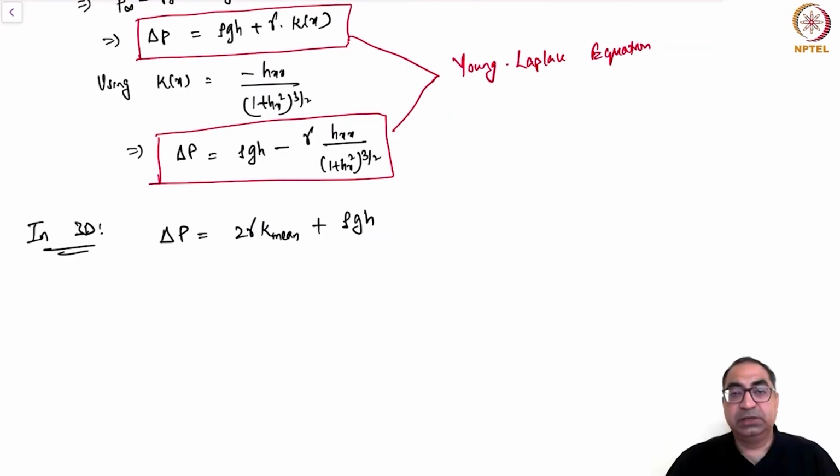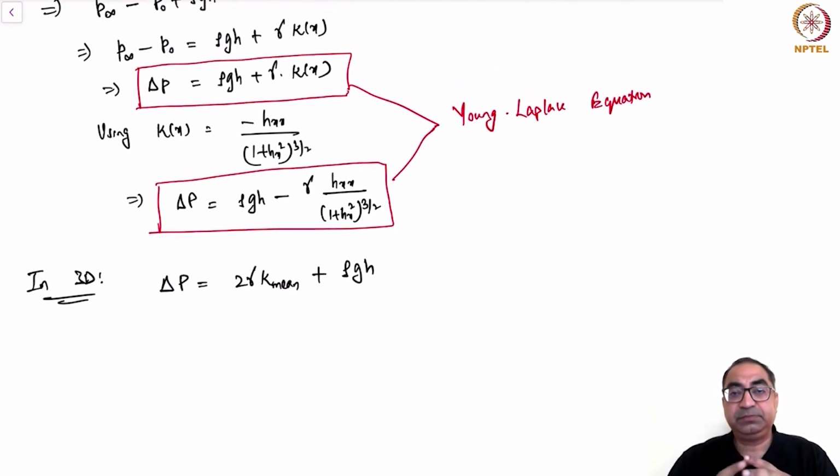Okay. So what we have done in this lecture is we have considered the case of a droplet sitting on a surface, and we have considered the variation of the height. If there are small variations in the height, this will lead to a variation in the energy functional. And this variation in the energy functional, we minimized it. We set the variation to 0, and in the process, we got boundary terms at the two contact lines that we have in the problem at A and B, and we also got the Euler-Lagrange equation.